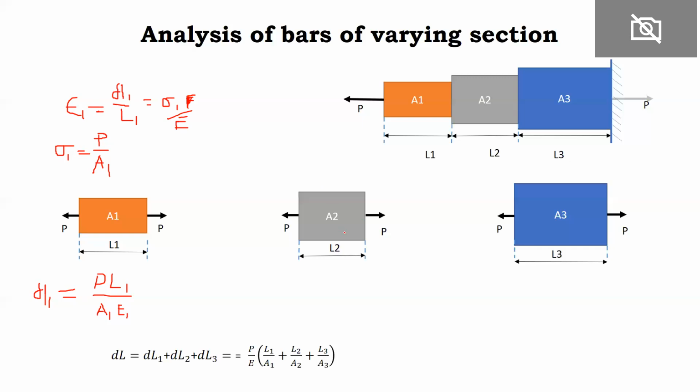Similarly, you can apply the same formula for computing stresses in the component. Young's modulus E is equal to stress upon strain. Similarly, you can compute the Young's modulus of the material if you know stress and strain. The same formulas are applicable here also. Stress, strain and displacement can be computed in member 2 and similarly member 3.